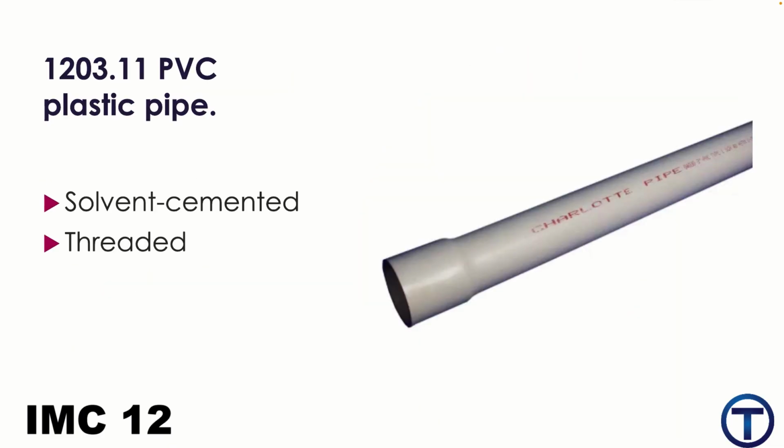Moving on, we have 1203.11, which is simple PVC plastic pipe. You know it, I know it. It can be solvent cemented or threaded. That's about all you can do, but make sure you're not using DWV.